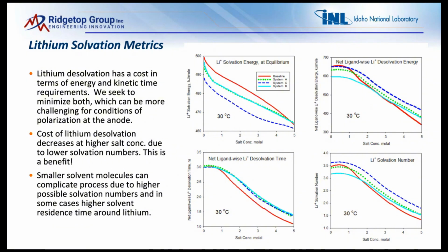That is a very clear indicator that the system is a good candidate for fast charging. When we built some coin cells and did some EIS measurements, based on the interfacial attributes of the Nyquist plots, the results corresponded very closely to this 10 to 15% reduction. So we're seeing good correlation between the pre-screening provided by AEM and what we're actually measuring and capturing in our cell data.